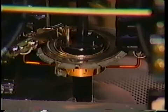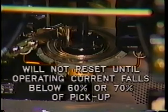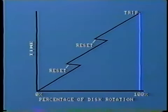Moreover, the disk will not reset immediately. In some relays, not until the operating current falls below about 60 or 70% of pickup. If a repetitive fault occurs, the disk may not have time to reset completely, and each repetition may cause the disk to creep forward, and so after 2 or 3 repetitions, ultimately trip. These limitations must be borne in mind when calculating relay settings.